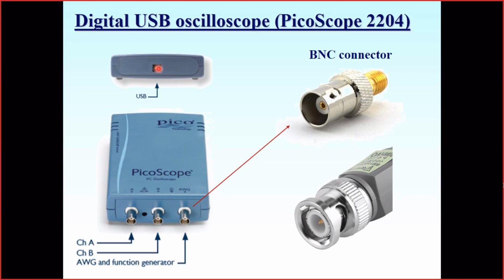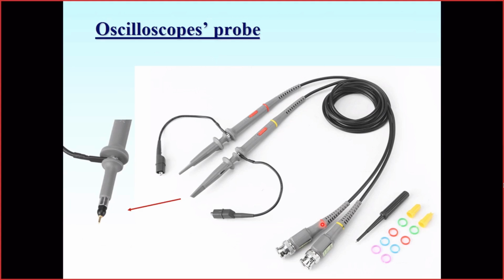So all the grounds are connected together. Please be careful when you work with a generator. Don't touch the signal, and don't touch any of the bodies of these BNC connectors or ground, because they're grounded with your generator signal pin, so you may get the generator damaged. On this scope, this crocodile connector is for the ground. You may attach it to the ground of your circuit to get some measurements.